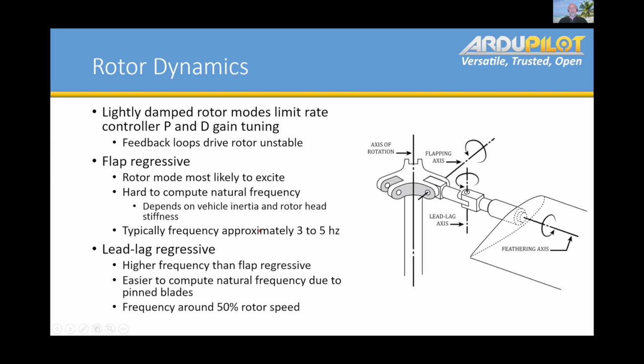And it's around 3 to 5 hertz. In the roll axis, it's probably 5 hertz. In the pitch axis, it's around 3 hertz. That frequency depends on the axis and its inertia, and it also depends on how stiff your rotor system is. I had a 4-bladed system on an Airbus X3 or Eurocopter X3 style helicopter that I had made homegrown, and the rotor flap and pitch frequencies were up around 5 hertz.